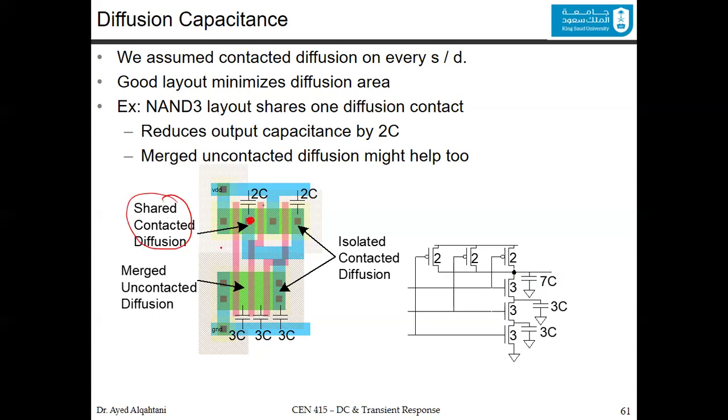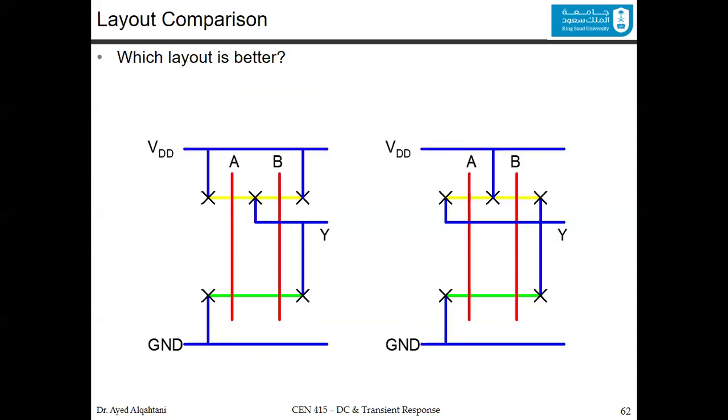Now, if you were asked which layout is better, this layout or this layout? This is a stick diagram, actually. This stick diagram or this stick diagram. Which one is better? You know that they are equivalent in functionality because you have two in series here and you have two in parallel in the pull-up. We did the parallelism in a different way from here to there.